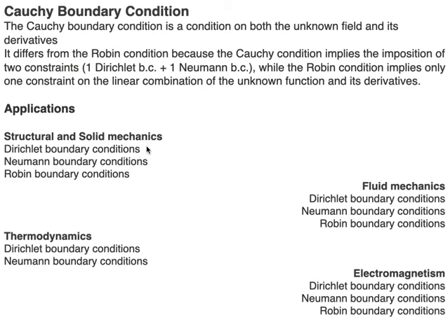Thus, direct boundary conditions usually consist of imposing the displacement of the structure at a given point, and structural mechanics is often based on a formulation which includes relative rotations, whose numerical resolution requires non-linear shape functions in the finite element approximations.